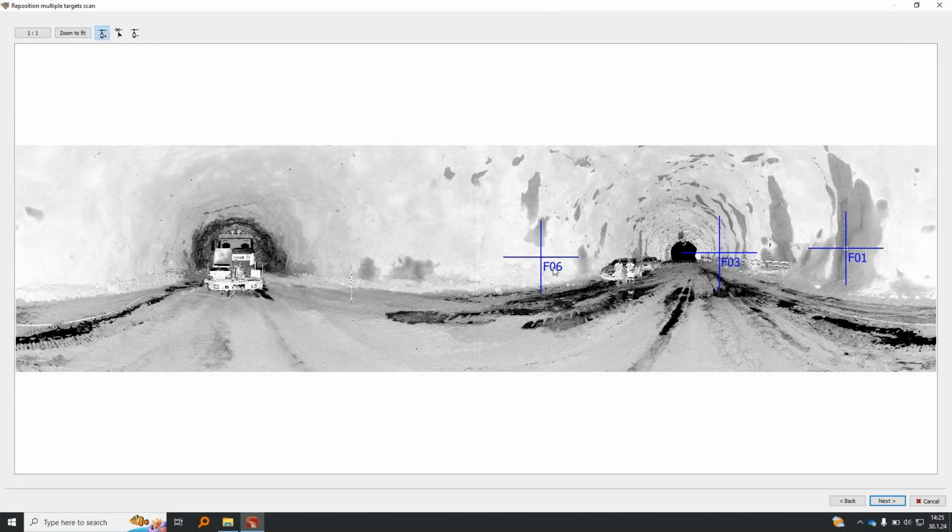So it's a very easy workflow designed for repeatability, to spend as little time as possible doing this daily georeferencing of the blast events, for example. We only have 3 spheres in this case. If we had more, we could of course pick another one and it would find the geometric match if it exists in the control point list in the project tree.